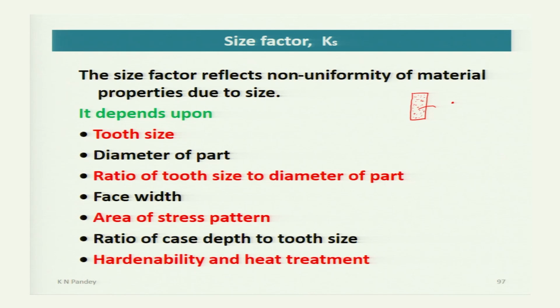Now it depends on tooth size, that means the module, diameter of part, ratio of tooth size to diameter of part, face width, area of stress pattern, ratio of case depth to tooth size, hardenability and heat treatment.